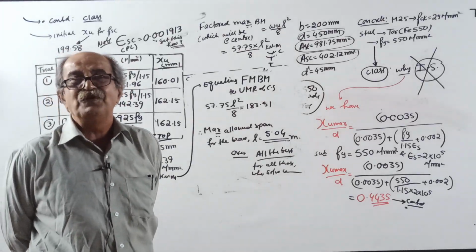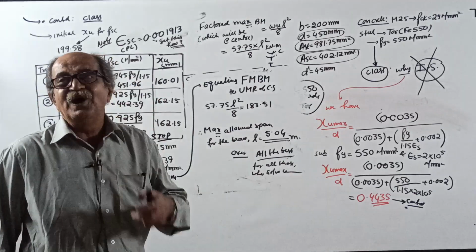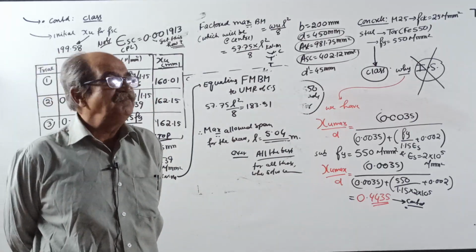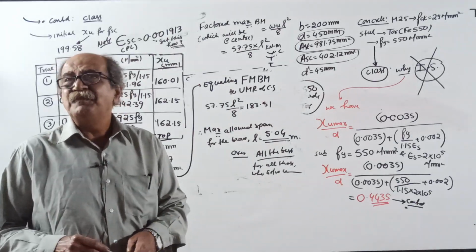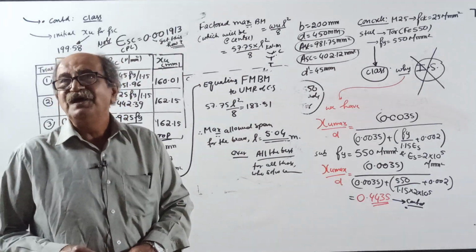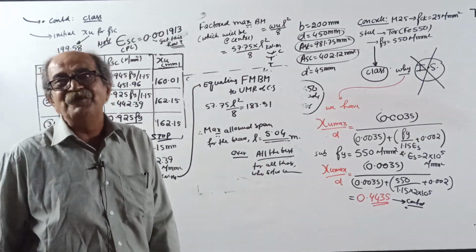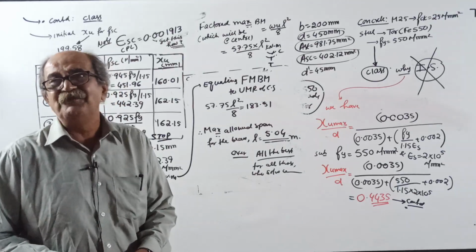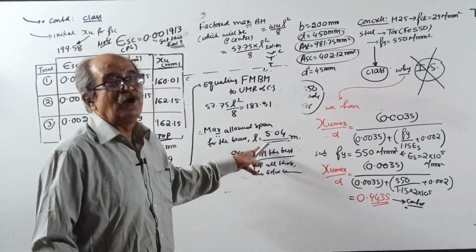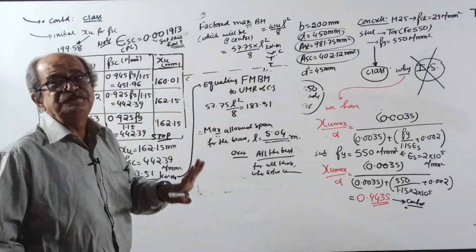Then I will tell them, factor of safety is for the load or material, not for span. Tomorrow, the member can be overloaded, no doubt. Material property may change, it may become weak. Today's 5-meter span, tomorrow will not become a 7.5-meter span. Then they will tell, oh, for span there is no factor of safety, there is no permissible span or factored span, only one span. Loading, we already consider the factor.